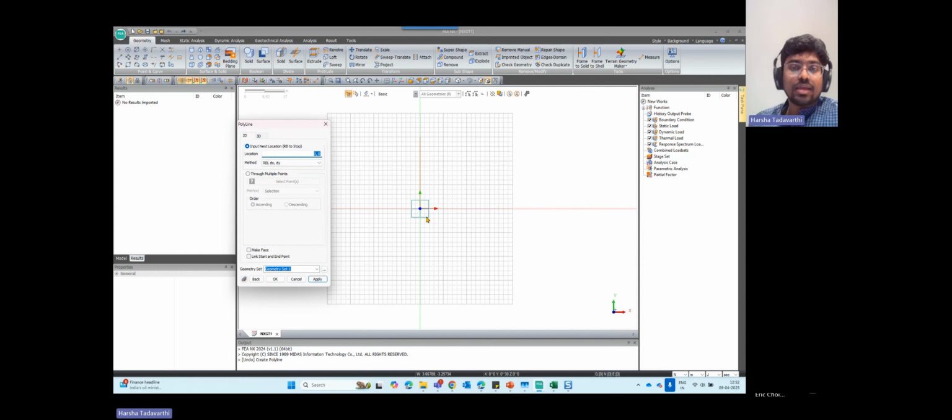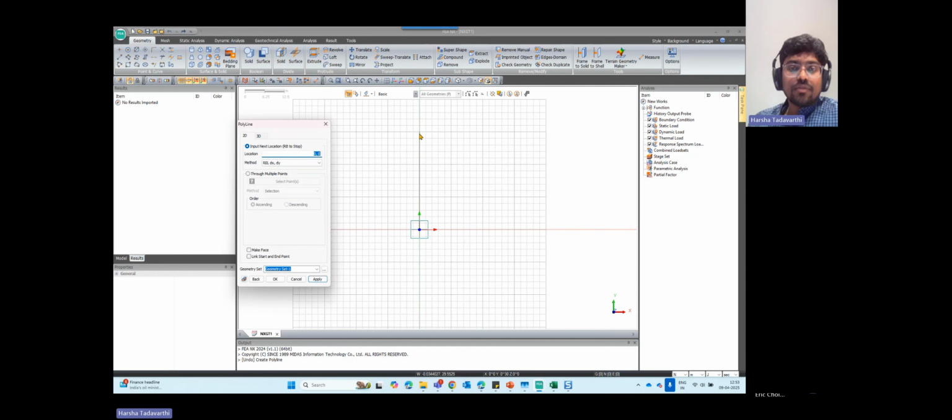So you can see a line has been created already, right? Then from here, we are going to provide the top width of the dam, which is 5 meters, and this is going to be in the X direction. So we are going to provide 5, 0.